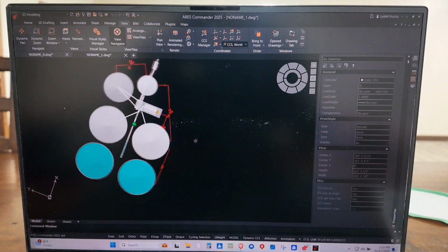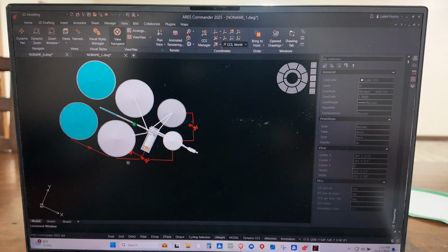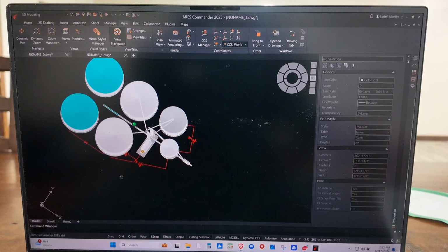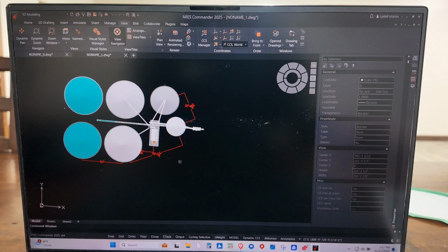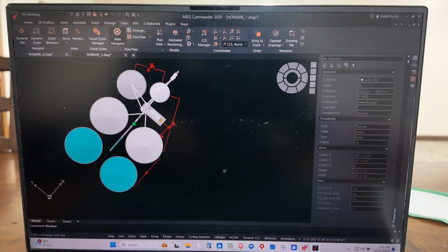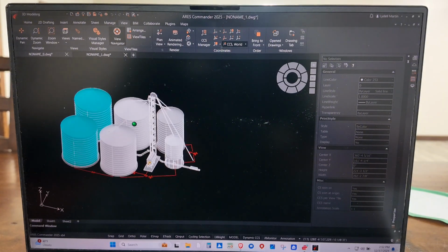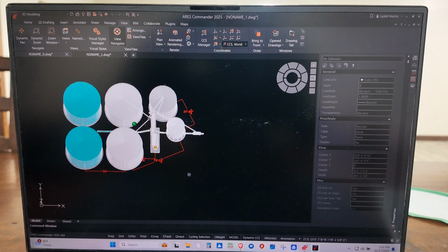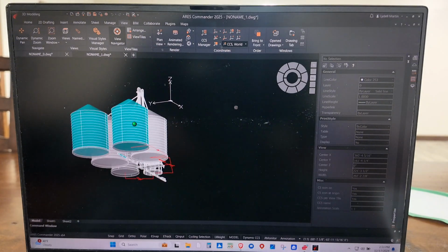You can sit down with him, show him the drawings, and you can make adjustments then. If the customer says, hey, I want this like this, that like that, you can make adjustments and move things around. Or if you're on site, you can look at the site, get measurements between bins for getting your bins placed correctly, so that your drawing matches the existing setup. And then each time you add on to the existing setup, you make sure you modify your drawing, and so you have an accurate drawing of what your customer's setup is.